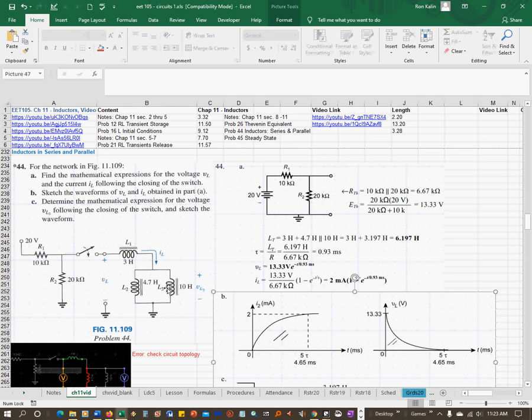So how do you solve this problem? Well, first thing is, since you have these two resistors that are in a neither series nor parallel configuration with everything else, you need to find a Thevenin equivalent. So again, you take this out of the equation. This is your A and B, because these are the items that you want to solve for. So you take them out, and then you just look at this circuit this way. This is your terminals A and B.